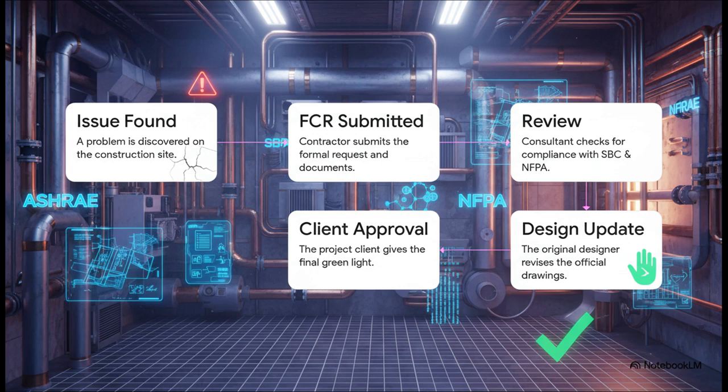First, someone on site identifies the issue. Second, the contractor puts together and formally submits the FCR with all the backup documents. This is where you do the heavy lifting. Third, the project consultant reviews it, and they're laser-focused on making sure it complies with codes like SBC and NFPA.